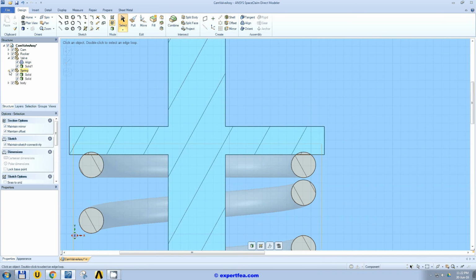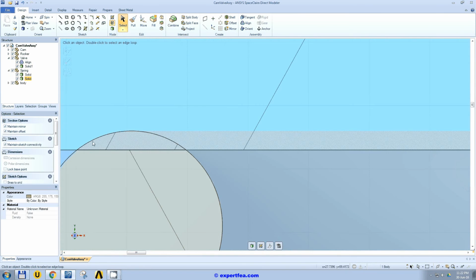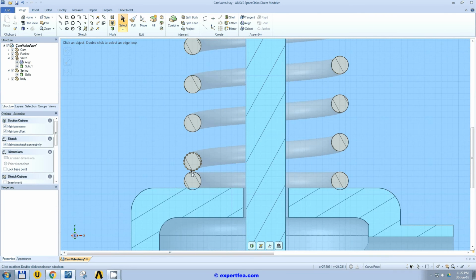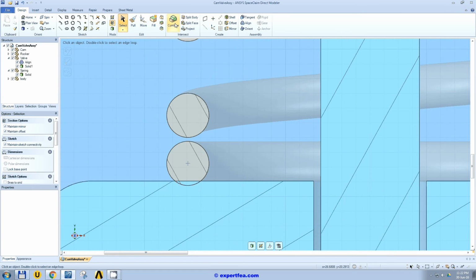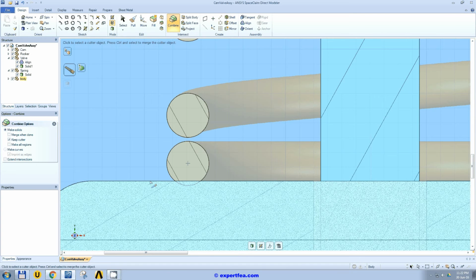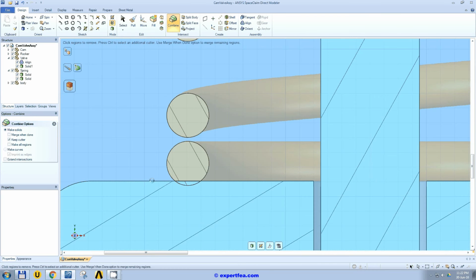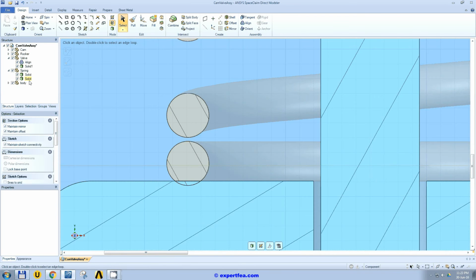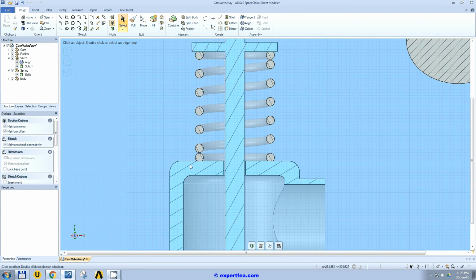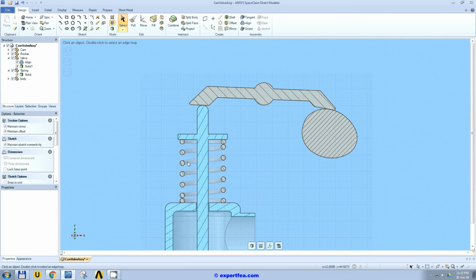Let's go to the spring and we observe this extra portion that we need to delete. Yes, now we have a very nice touching surface. Let's repeat the command. Combine, the spring is the target, it should be cut with the body. Escape. We select this extra portion, click delete, and that's all. This is what we need. Alright.